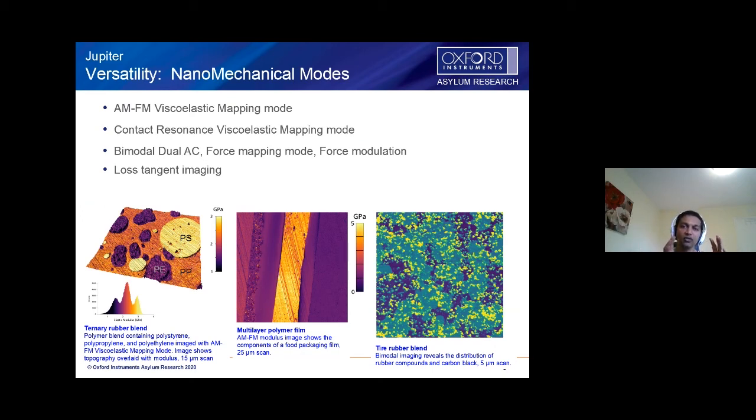However, in case of AFM, you are able to measure very thin films and get results where you don't have the effect of the substrate because the control of the tip sample forces is much more accurate than a bulk nano indenter. So the short answer is yes, you can use this AFM that's at UT Dallas to do indentation experiments on 100 to 500 nanometer films. And if mechanical measurements are of more interest, I'm happy to give another detailed talk on that topic.